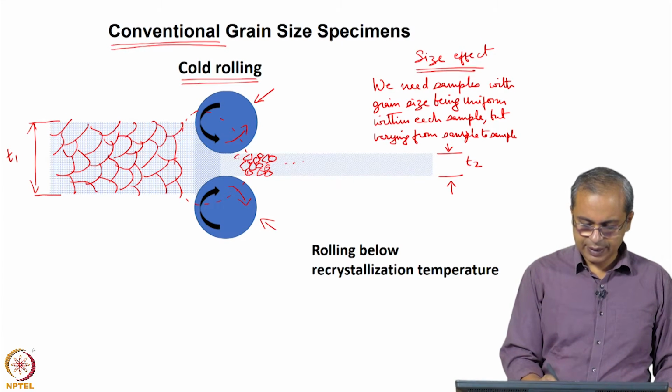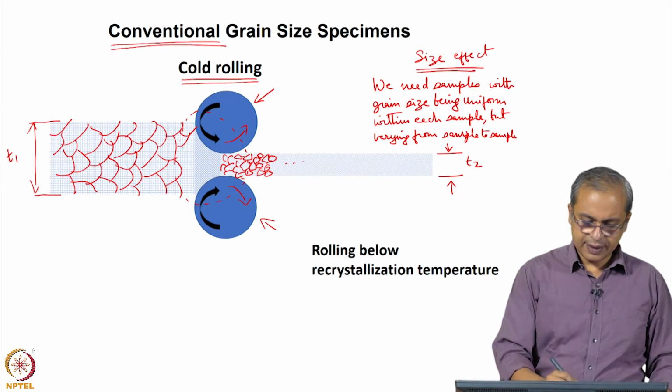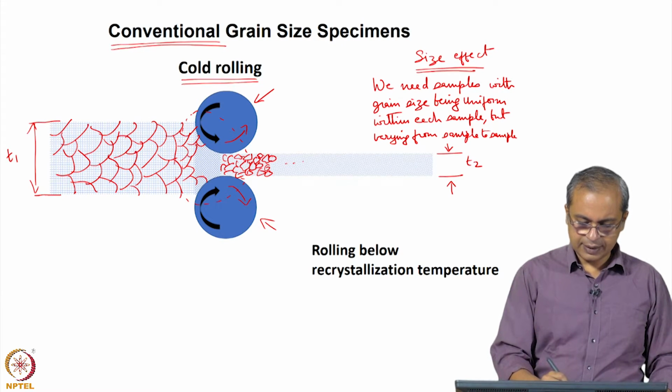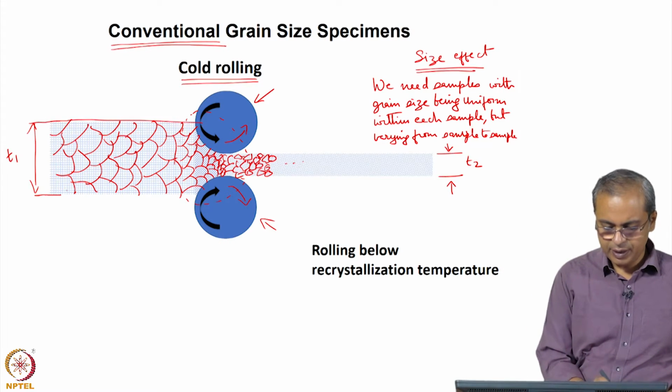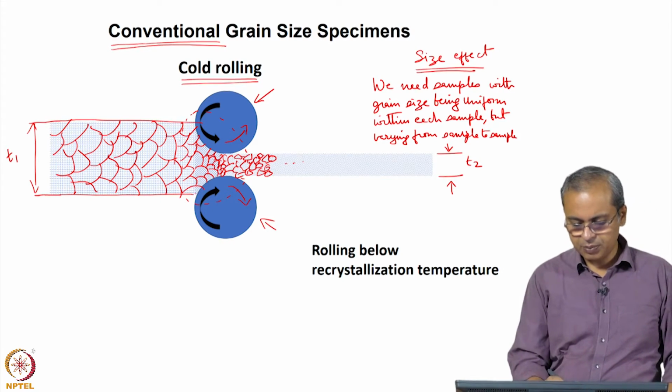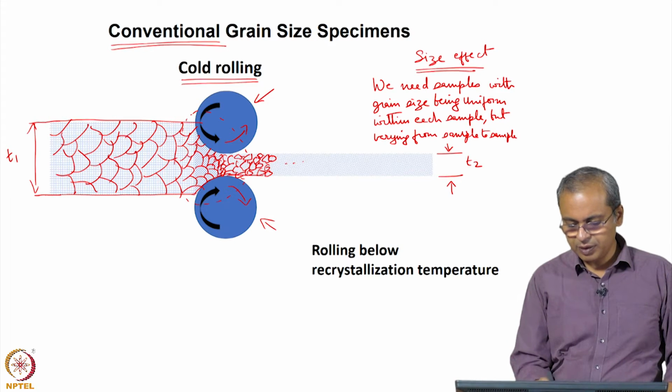So, that continues in that direction. And in the transition region, slowly it goes from larger grain size to smaller grain size. So, that is basically what you start seeing. Yes. So, you see something that starts off as a large grain size material out here, and then as it gets squeezed, it slowly becomes a small grain sized material and comes out this way.